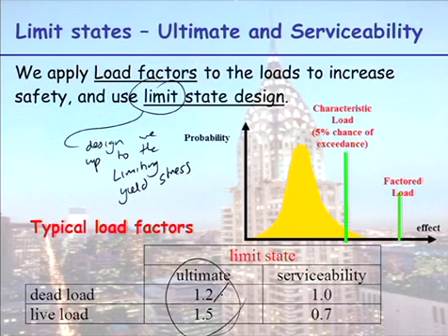No, you're allowed to stress it up to 249.9999. And then you don't go, oh, that's too close, that's about to fail, because your factor of safety is in your loading. You've put extra load on. So we call this limit state design, and that's to compare it to permissible stress design. In permissible stress design, you actually put the true load on, and then you don't load it up to yield. You load it up to maybe 70% yield.